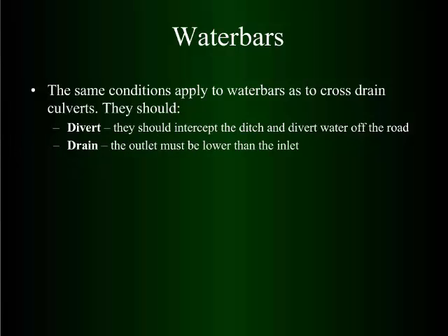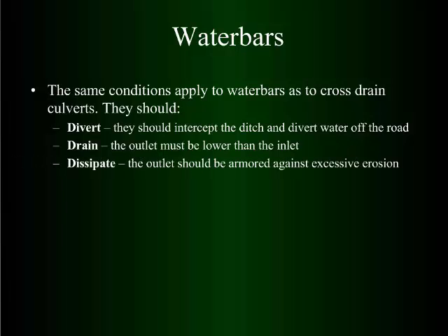Well, you probably figure that water doesn't flow uphill, so best to have the outlet lower than the inlet. And we talked about energy a little bit, but you need to get some dissipation on it. I talked about the ditch-out not accelerating the water. You can dissipate it by having it splash on the rocks and spread it out somehow, or basically take the gradient out, so it loses its energy before you disperse it. And then the distance between them, and this is something.